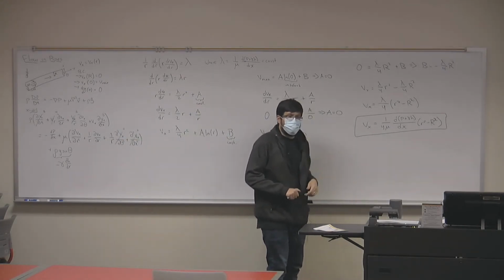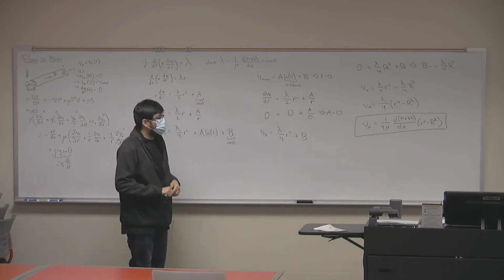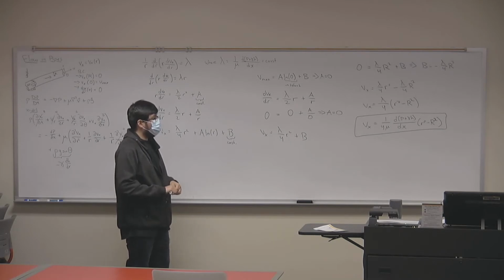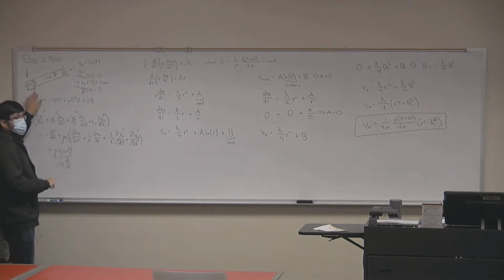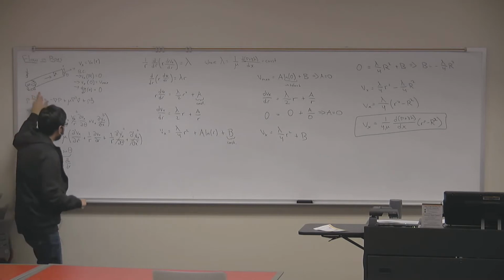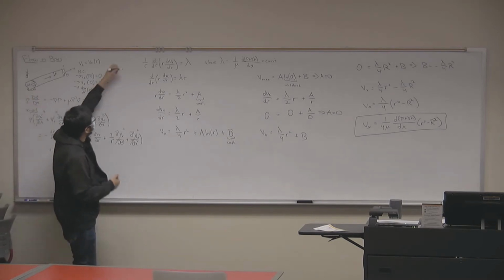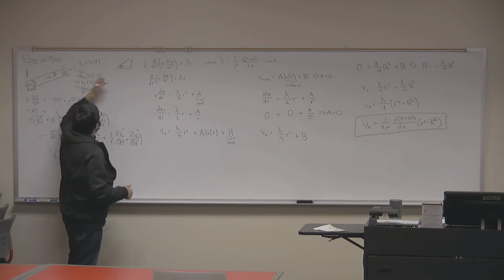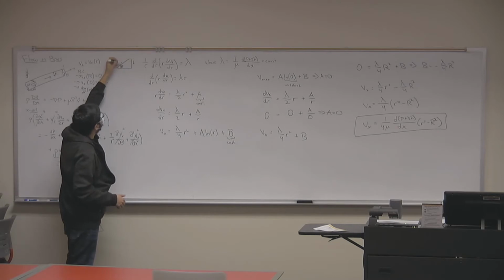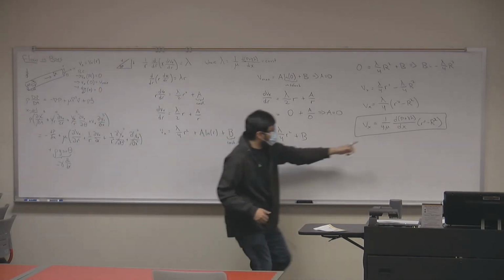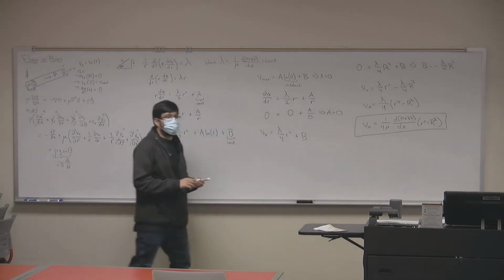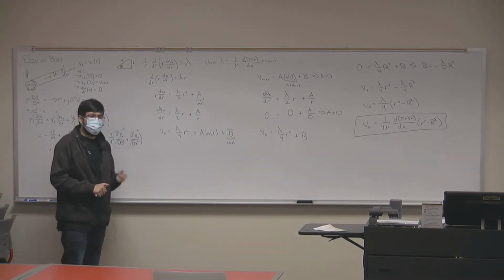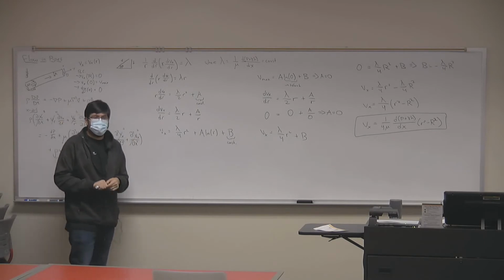Any questions? Yeah. So in your final equation, you don't have any theta in there, so would that mean that the angle really doesn't matter? Are you referring to this theta? Yeah. So this theta, and this is something that I skipped, but we covered in the last video. This theta is related to your drop h and your distance x through this dh/dx. So that's where the theta comes into play. Normally, we try not to express it in terms of theta. We try to express it in terms of pressure drop. Yep. Any other questions?